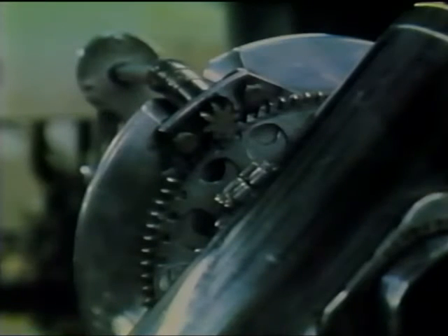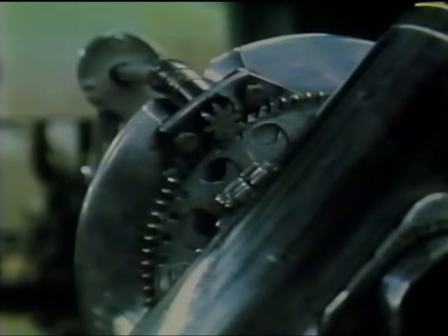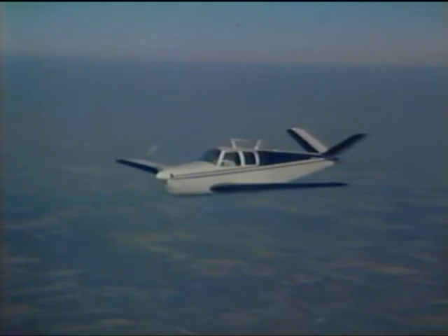When the crank handle is turned, a flexible cable turns a pinion gear mounted in a bracket directly behind the propeller, which meshes with a drive gear fitting around the crankshaft and mounted to the engine crankcase. The drive gear is mated to the actuator, which rotates the blades on the propeller. Some installations of controllable propellers may incorporate the use of an electric motor to move the drive gear, using only a simple toggle switch in the cockpit.